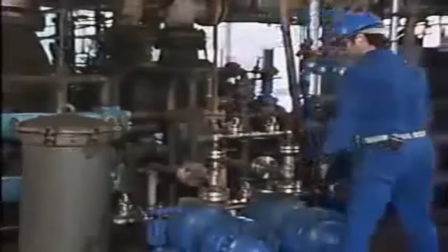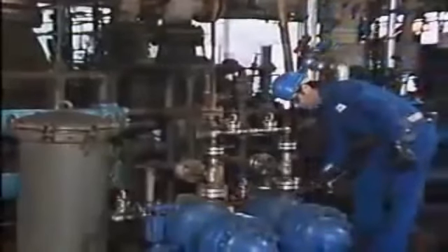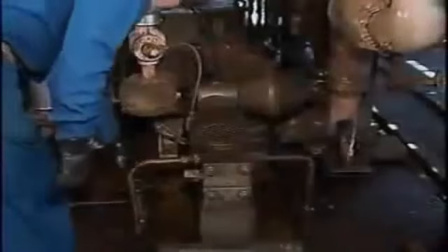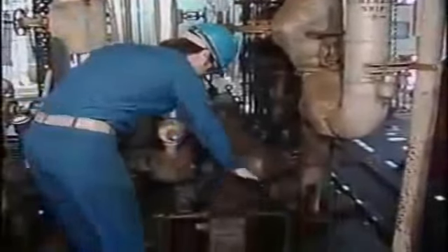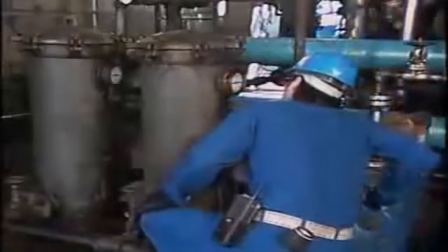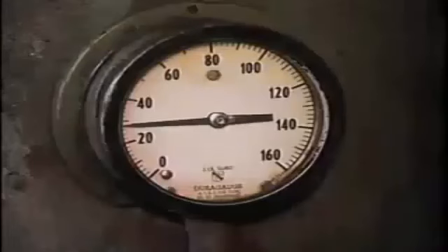These valves must be open to supply lubricating oil to the compressor. Once the operator is sure that all of the valves are properly set, he starts the compressor auxiliaries and makes sure that they're operating properly. For example, this lube oil pump has a steam-powered driver. It's started by opening the valve that supplies steam to the driver. Then, to make sure that the pump is working correctly, the operator checks the lube oil supply to the compressor.